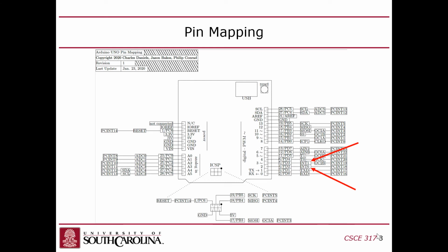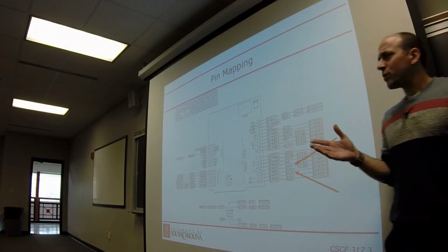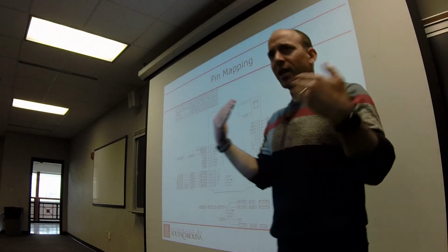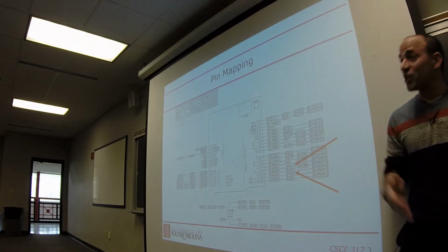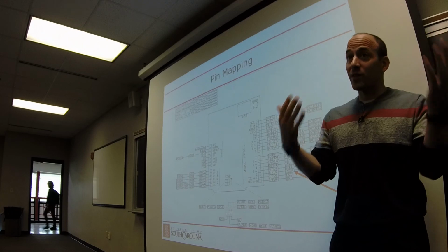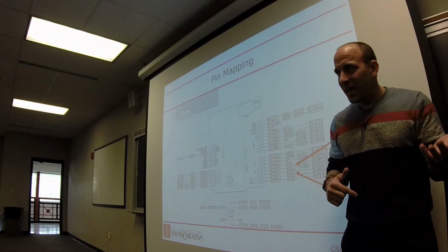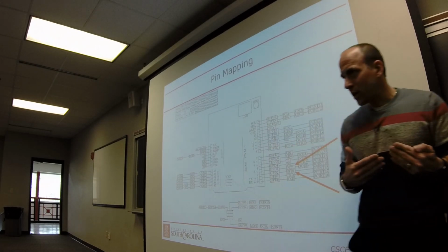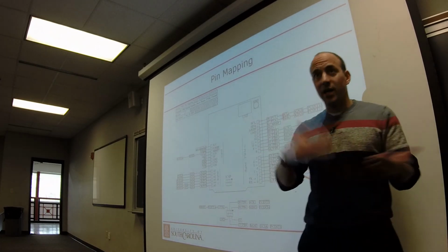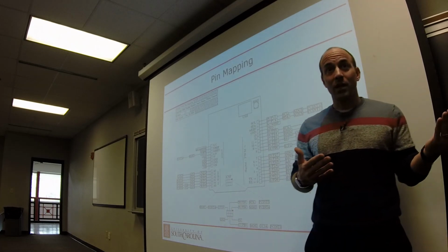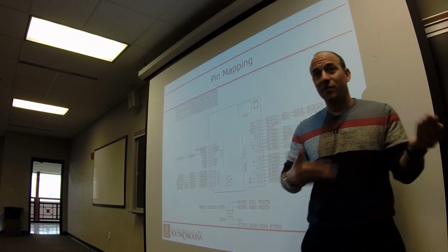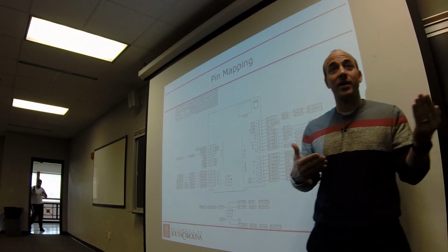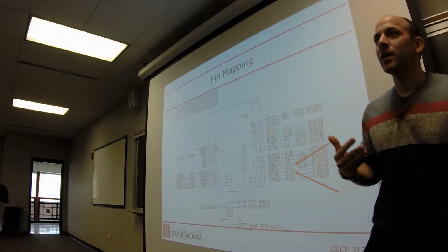First of all, let me step back here a minute. What about this interrupt? Are any of you trying to use the interrupt? An interrupt is a signal that an external device sends that gets the attention of the processor, which means that if you have a laptop, every time you hit a key, an interrupt is fired, right? Every time a packet is received from the network destined for your computer, an interrupt is fired, right? And if I send your computer packets at a fast enough rate, it'll trigger interrupts so fast it'll livelock the machine. It's a denial of service attack, right?